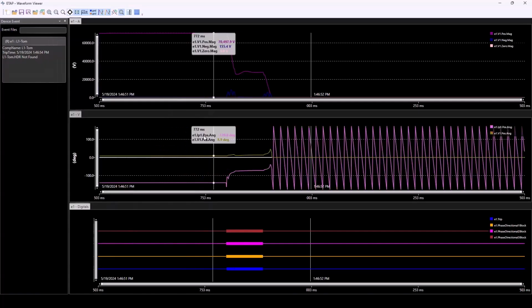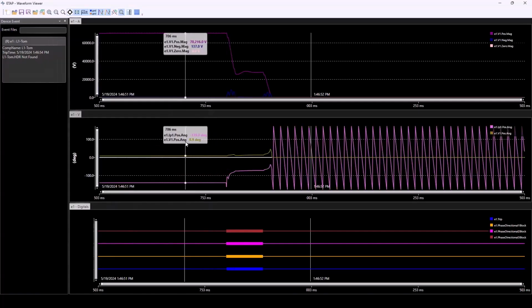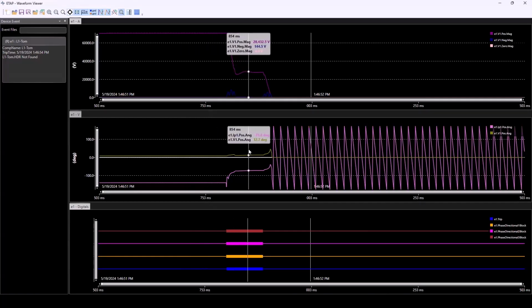All right, so as you can see here, the angle difference between I1 and V1 during the fault is about -73 minus -12, which is about -85 degrees. This information is crucial in evaluating IBR performance during a fault. Accurate analysis of these signals helps ensure that the IBRs are performing optimally and meeting the grid code requirements, which is essential for maintaining system stability and reliability.